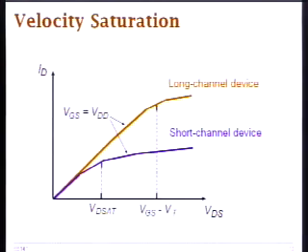So that was the main difference between a long channel device and a short channel device, in the sense that the short channel device, due to velocity saturation, would experience this long saturation region. So now the question for you. Let's assume we have this curve, and then the question is, why don't we use a long channel device? Because it has more current. What's the reason we still, excuse me? Leakage. Other reason, space, that's a good one.